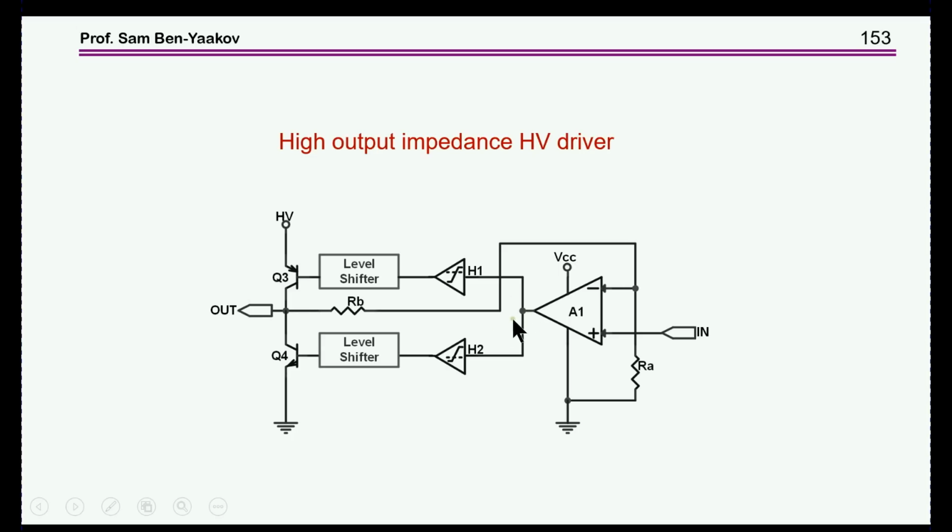We do have a window here, a hysteresis you might say, such that when you are at the right operating point, none of the transistors is conducting. Only when you need to change the voltage, it will excite either this one or this one to inject a little bit of charge into the midpoint and therefore change the capacitance. So this actually consumes very, very little power, because there's just a little bit of charge to inject here.